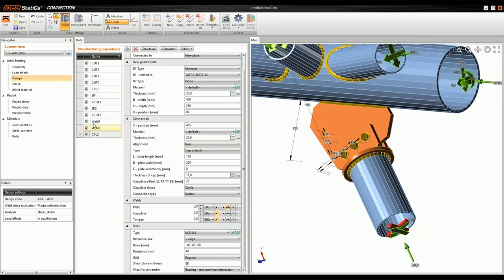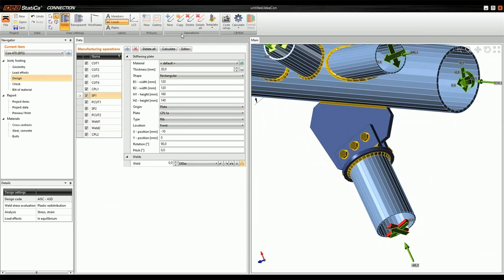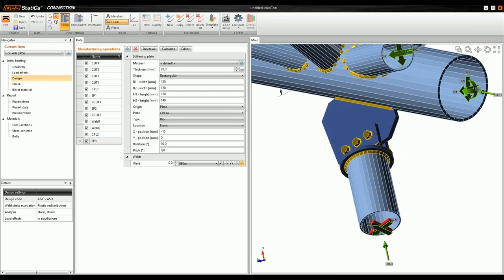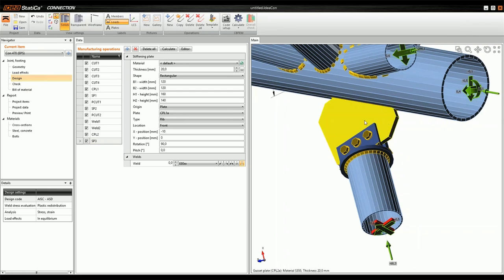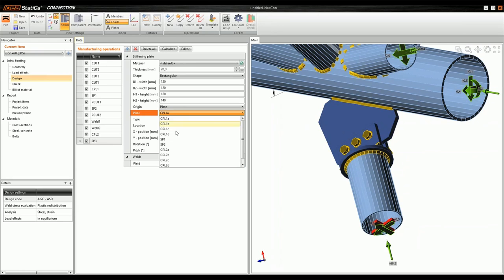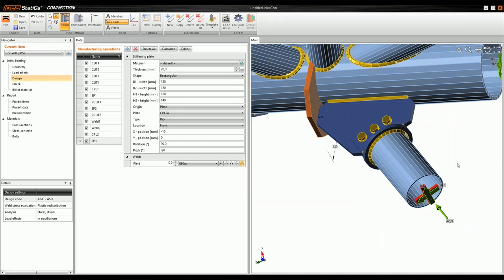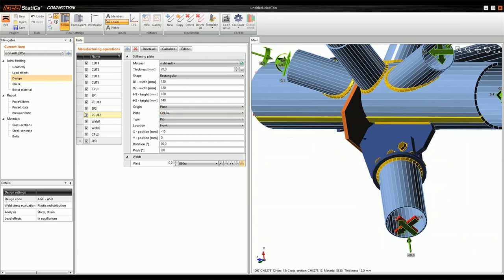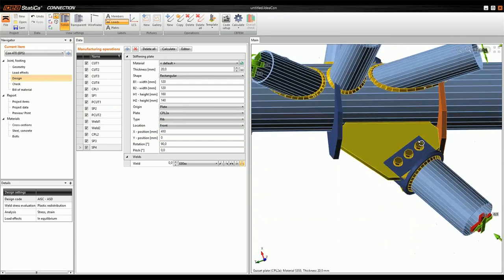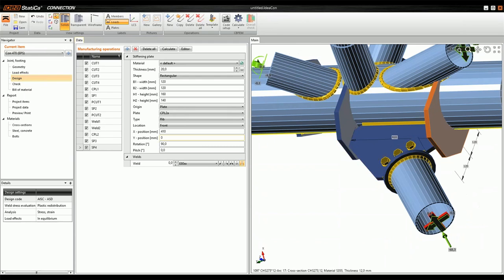Better look. And now I'll just copy the stiffening plate for this connecting plate, which is CPL 2A. Okay, we got it here. And I will also copy it on the other side. So like this. And I will just weld them all together.